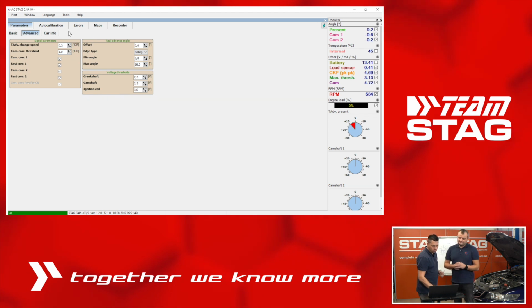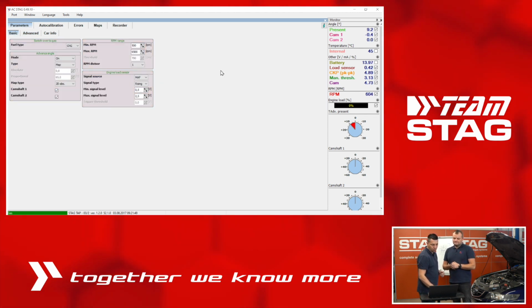Okay, and I have one more piece of information, because we had also a question about this. Sometimes when you do the auto-calibration, TAP will read all the parameters, including the RPM parameter, but the RPM parameter is not the same as you can see on the dashboard in the car or in an OBD reader or external scanner connected to OBD. Sometimes after the auto-calibration, the RPM value is 2 times higher or 3 times higher, or even lower. Lower, yes. So you can check one thing.